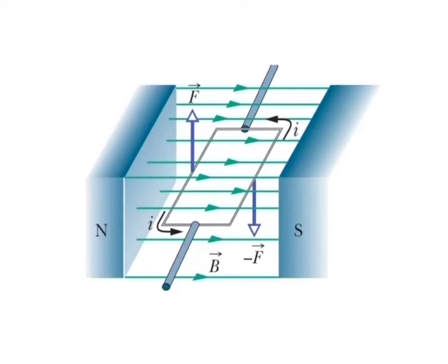The two magnetic forces acting in opposite directions produce a torque on the loop tending to rotate it about its central axis. Although many essential details have been omitted, the figure does suggest how the action of a magnetic field on a current loop produces rotatory motion. Let us analyze that action.